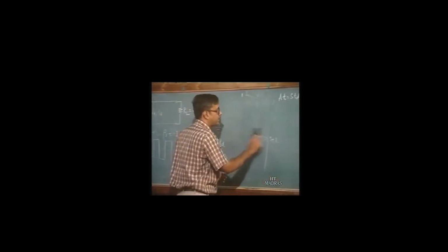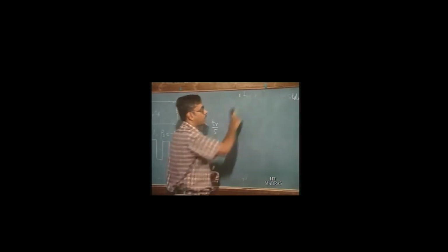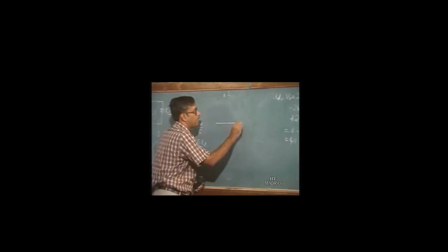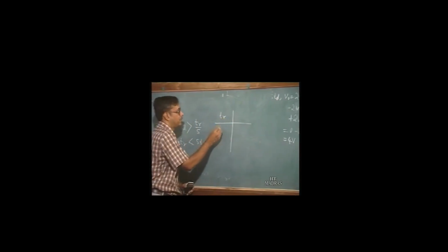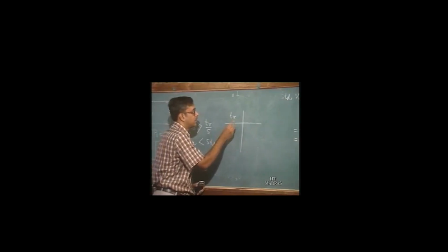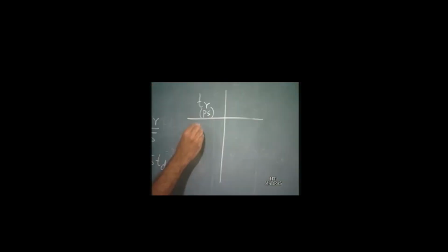Now if we look at the different rise times, for example, say you have 1000 picoseconds, that is 1 nanosecond of rise time, then what is the critical length of a line when you have to start thinking of the transmission line effects? That is what we have to consider.